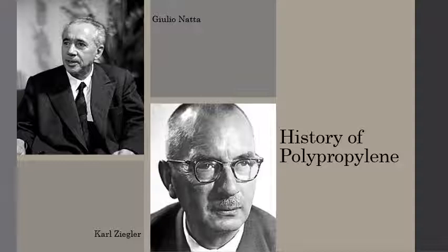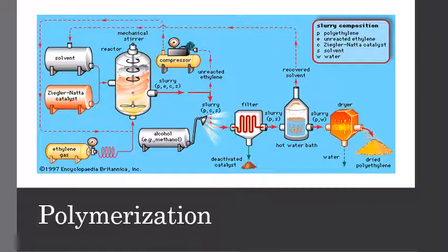To begin this process of making a fabric, first the monomer propylene is extracted from crude oil in its gaseous form. This monomer propylene is then subjected to a process called polymerization. During polymerization, there has to be a catalyst, typically Ziegler-Natta or a metallocene catalyst, in order for the reaction to occur. The manufacturer will set the polymer grade to be produced, which then sets the conditions of temperature, pressure, and reactant concentrations. There are two processes that exist to produce polypropylene: a liquid phase process and a gas phase process.